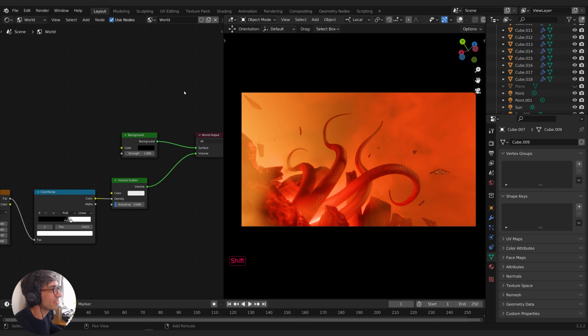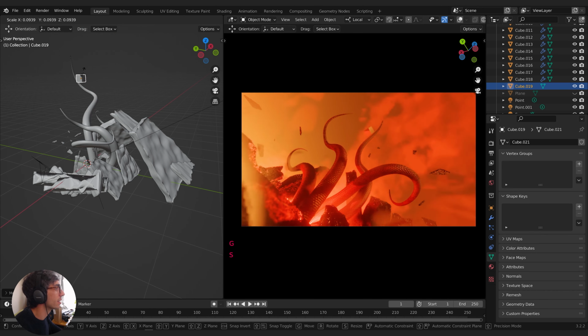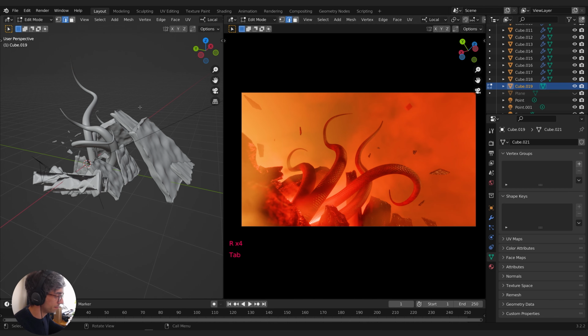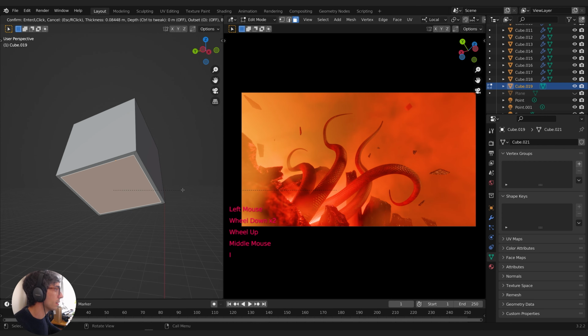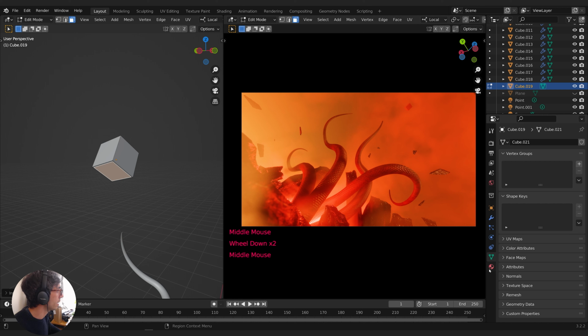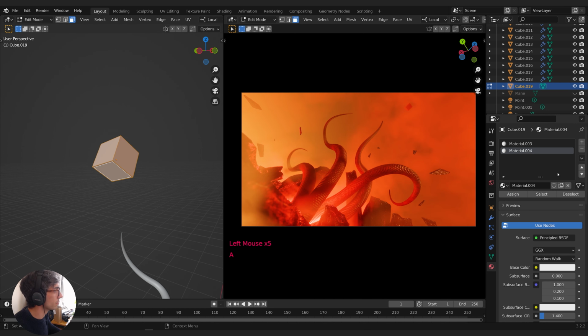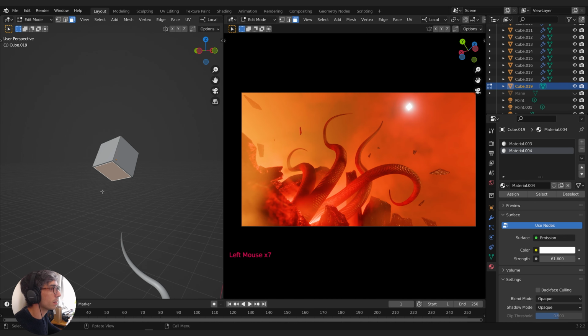All right, let's make this thing escaping. I'm going to go to 3D viewport, Shift A, mesh cube, grab Z, scale it down. I'm going to put it right about here, rotate Y. Go into edit mode. Go to face mode. Inset. And let's add a material. Let's add 2 materials. Actually, first we'll assign the first material to everything. Then I'll grab this face, grab the second material, and just assign that. We'll set this to be an emission. Turn it right up.